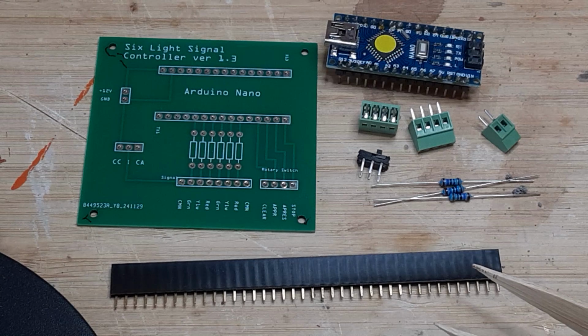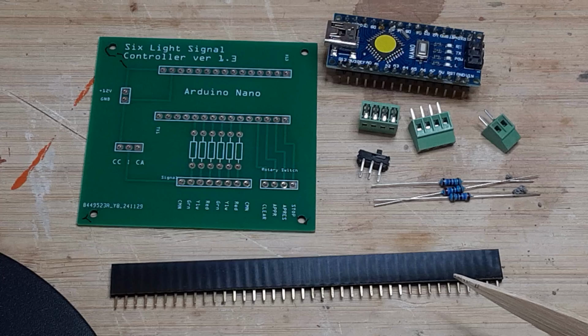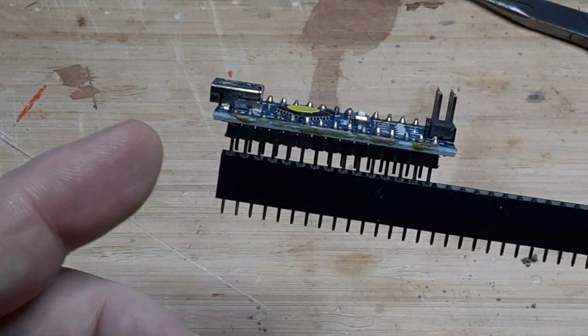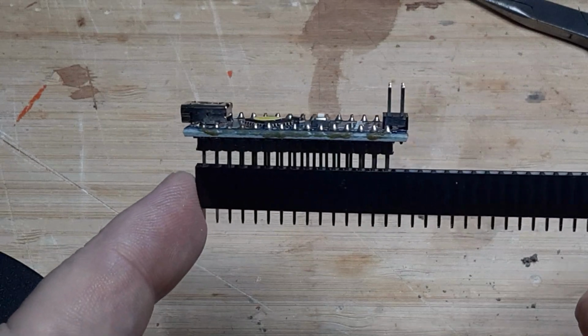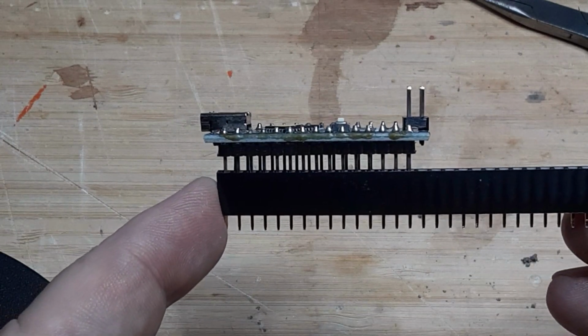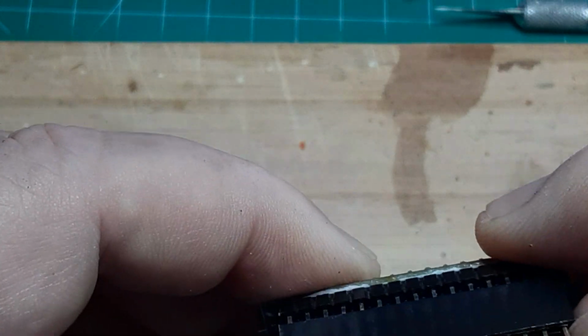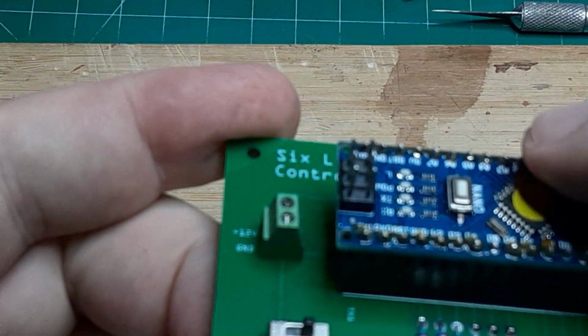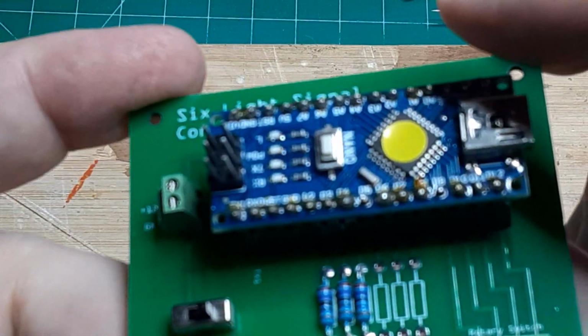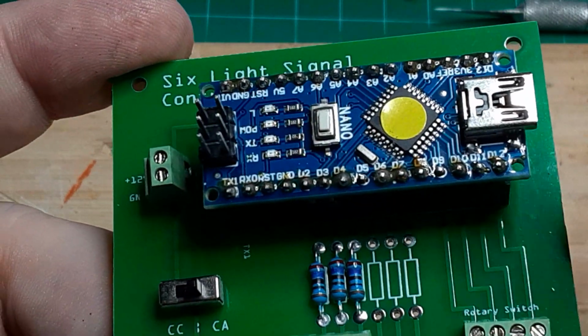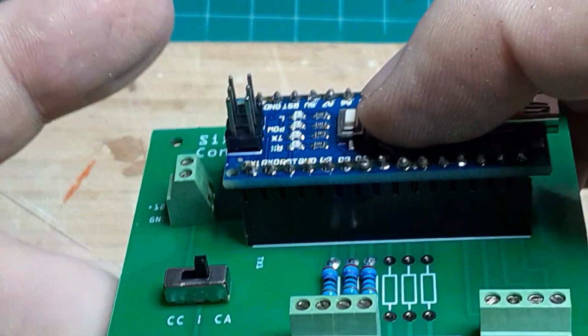To assemble this board, solder all of the parts to the board as before, saving the header blocks for last. As you can see, the header block is too long. The Arduino Nano has 15 pins on each side, so you'll have to cut 2 15-pin pieces from the 40-pin block. Plug the Nano into the 15-pin header blocks and fit the assembly into the printed circuit board. This ensures that everything will align perfectly and allow the Nano to be removed and reinstalled later.